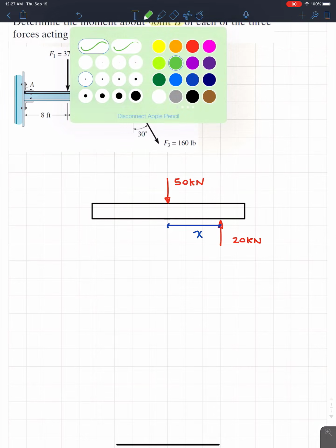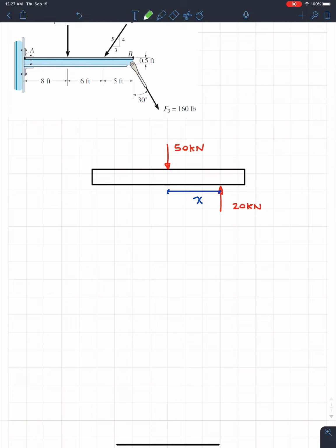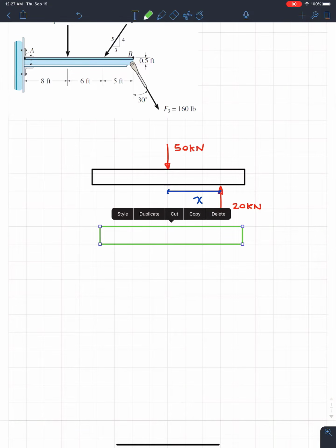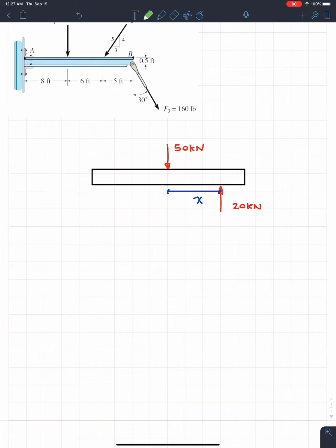As you guys can imagine, there's still more force going vertically downwards than there is upwards. So the beam will actually still move downwards. The only difference now is that it's going to start to rotate because of that difference in, well, moment, realistically. So the beam will actually start to look like this in the end. Let me just draw a fake beam by myself, like this. So this is kind of what you would see. It still moves downwards, but it also has that rotation.